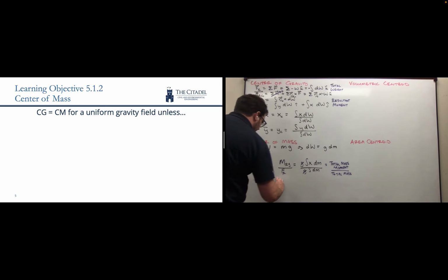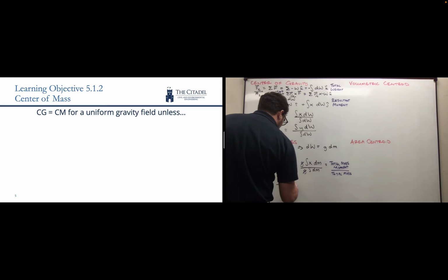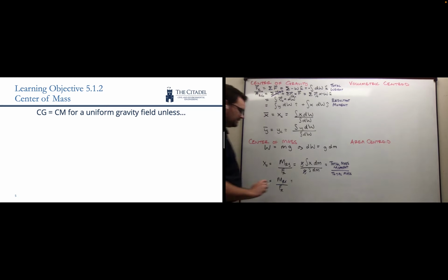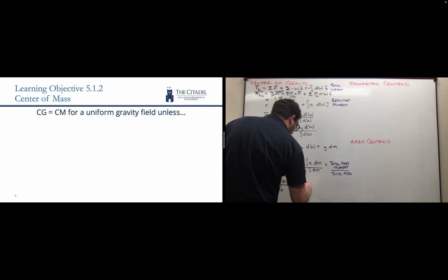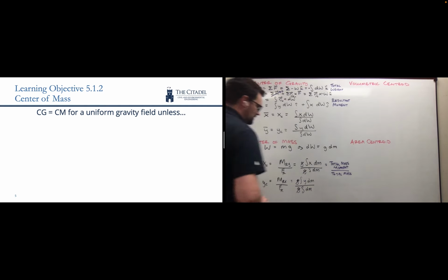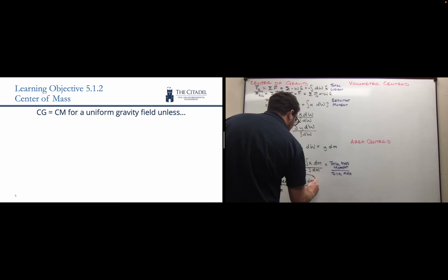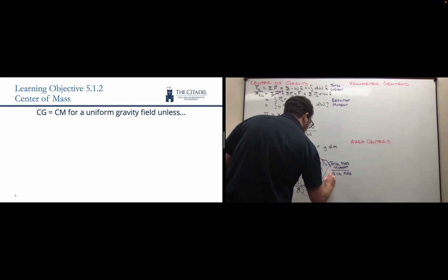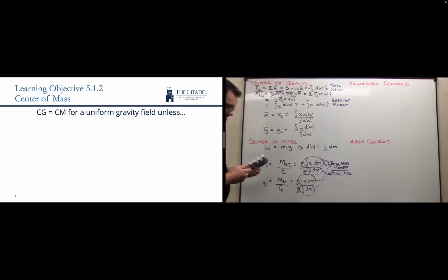And we would have the same answer for our y centroid. So the resultant moment about the x-axis, remembering that that's perpendicular distance in this case, will be the y direction, g times the integral y dm divided by g integral dm. My g's will cancel, and so again, this is a mass moment, perpendicular distance times the mass, and then these are my total masses.